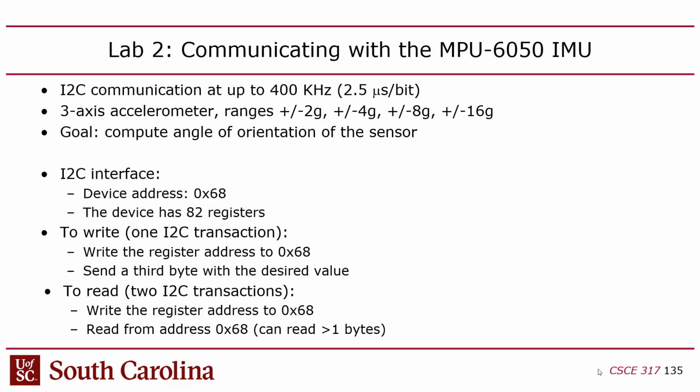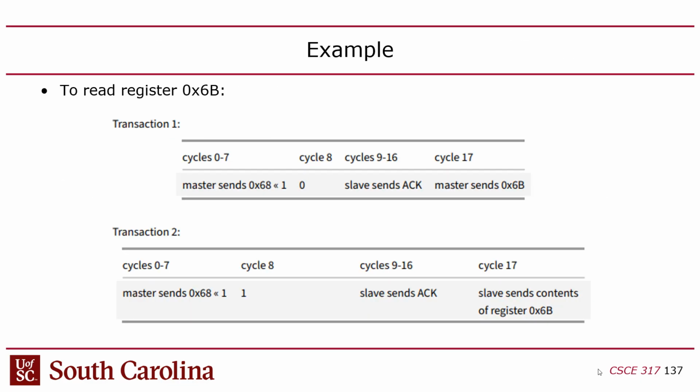The problem is that this is software controlled, so your software is going to have to enforce that speed, because it's not being driven by hardware. So you have to program it to be 400 kilohertz. You don't really have to do that, though. You can go slower and it'll still tolerate it. Just don't go faster.